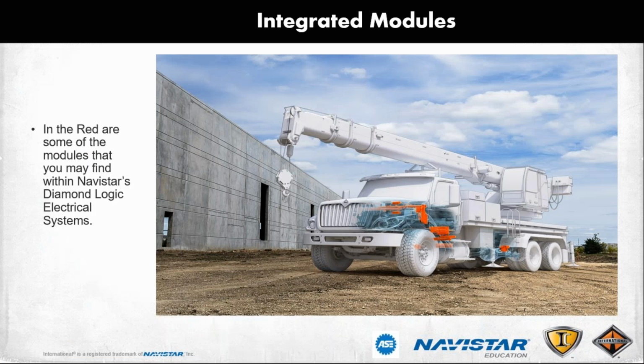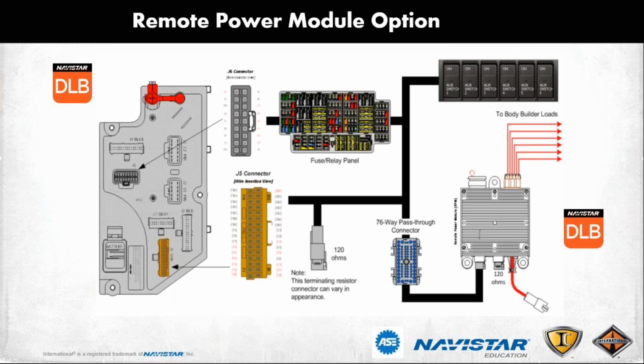So these outputs will default from the factory turned on to 20 amps. They're fully programmable in 1/10 of an amp increments, from 1/10 of an amp all the way up to 20. So if you're running an LED light or a string of them, and you know it only draws 4 to 5 amps, probably don't want to leave it fully turned on to 20.